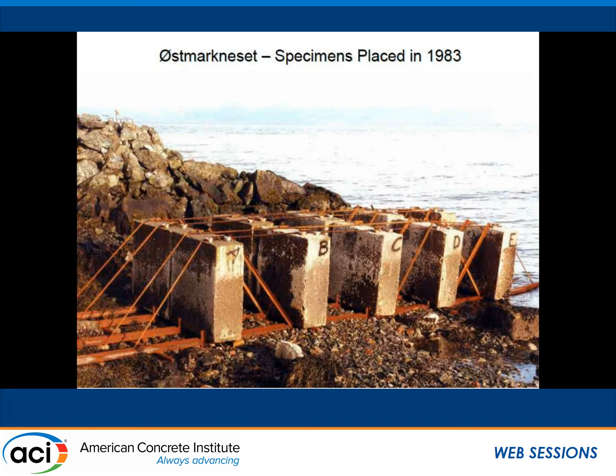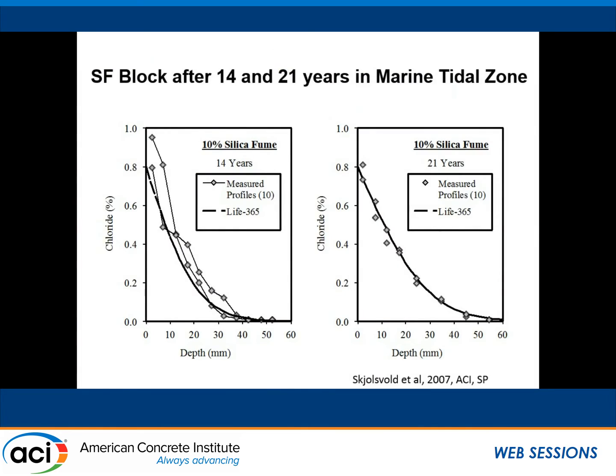These are some silica fume concrete blocks that are in the Trondheim Fjord in Norway. They've been out there over 20 years now, and we actually use Life 365 again to predict the experimental profiles. And I'll just draw your attention to the latest age data, 21 years. The Life 365 pretty much nails the profile very accurately. So again, for marine exposure, Life 365 really is a good indicator of chloride ingress.